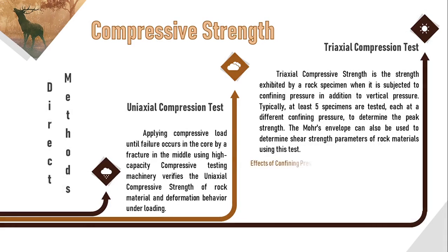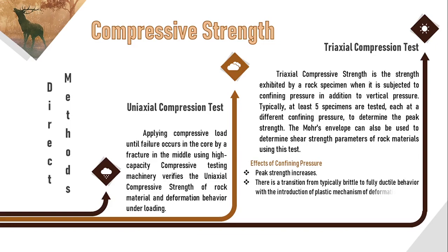Effects of confining pressure. Peak strength increases. There is a transition from typically brittle to fully ductile behavior with the introduction of plastic mechanism of deformation. Effects of pore water pressure. Transition from ductile to brittle behavior.